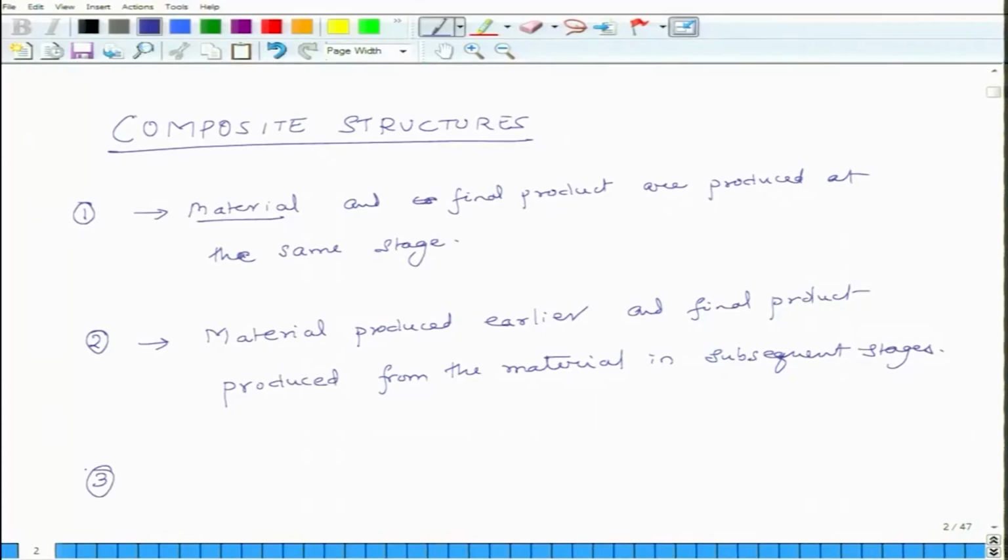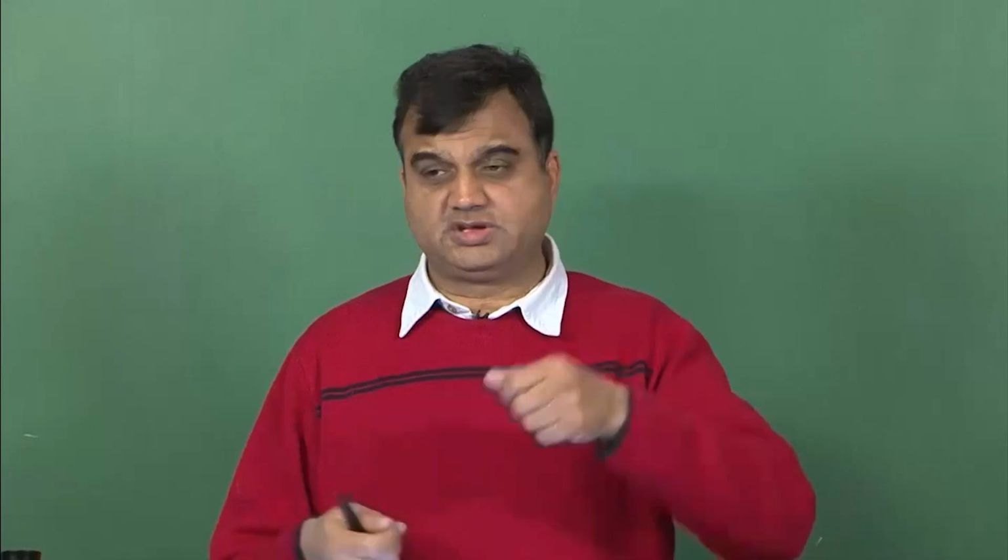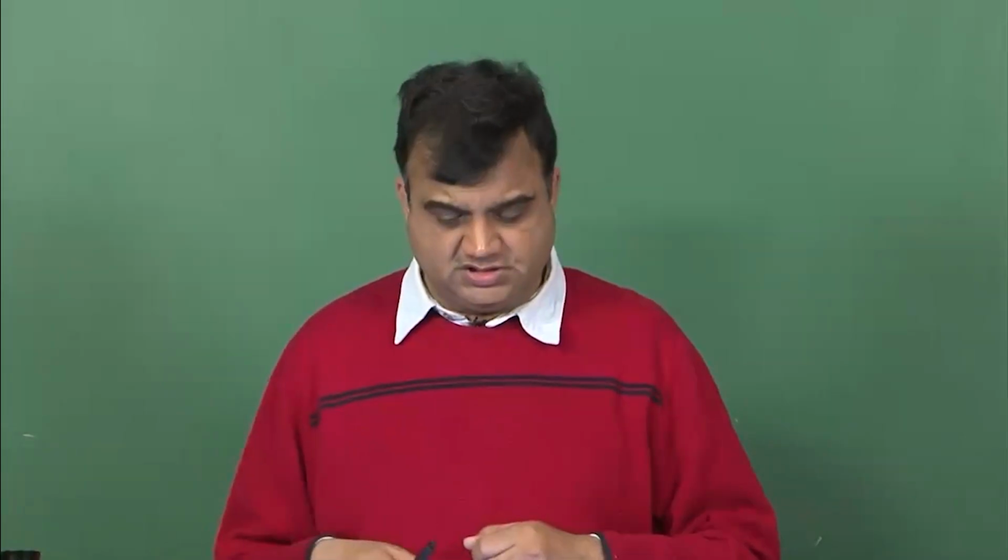So, this is the second scenario, and then there is a third scenario, and the third scenario is that you produce intermediate materials. These intermediate materials do not have the properties of the final material. For instance, a continuous fiber composite is made up of matrix and long fibers. So, they are two separate parts, you somehow mix them and you get composite out of it.